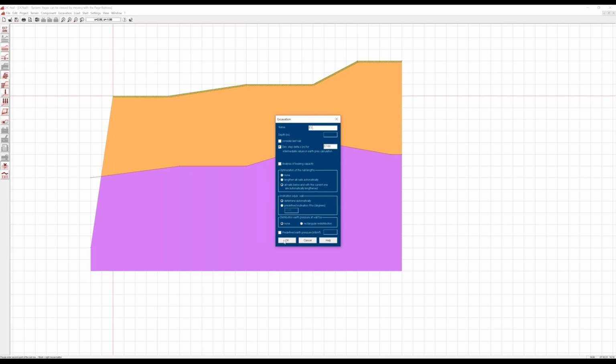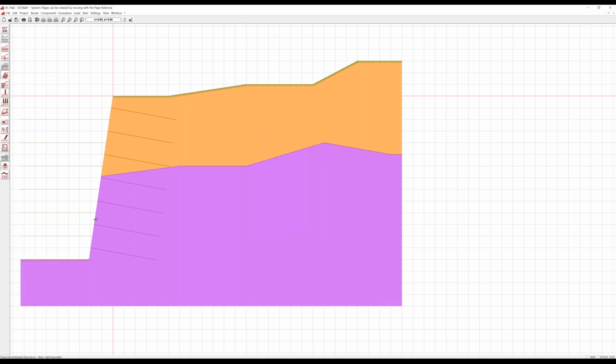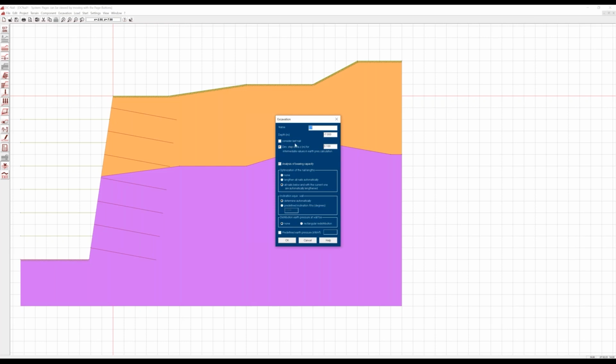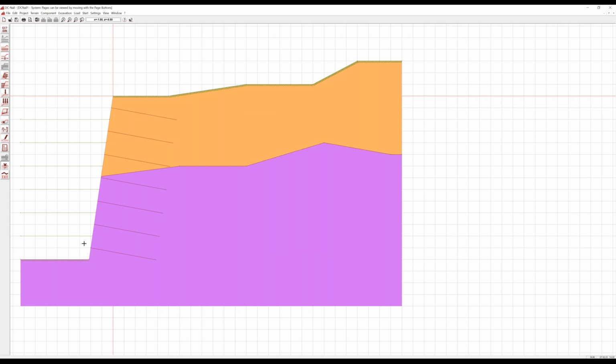So if I confirm here the excavation stage, all the stages are defined automatically. So we have in total 7 excavation stages and 7 nail layers. And in each excavation stage, we have switched off to consider the last nail. So we first have to excavate here and can then enter this nail layer. So finally, we need one excavation stage where the last nail is acting.